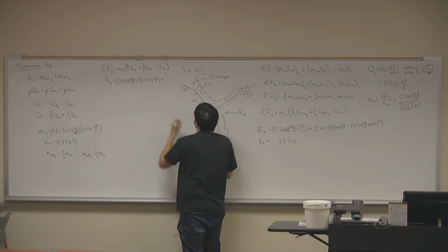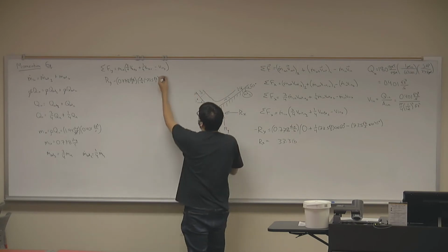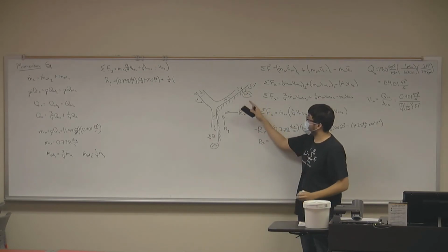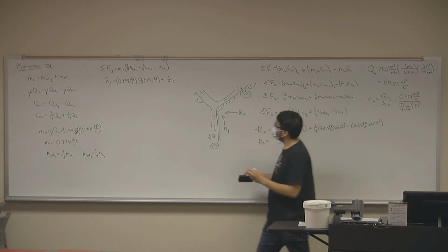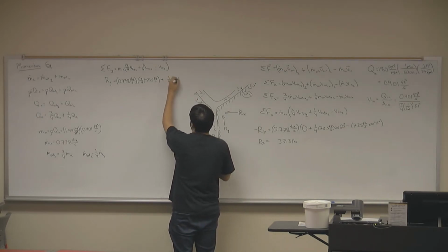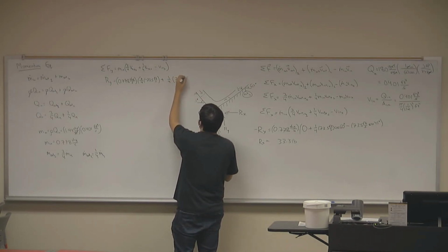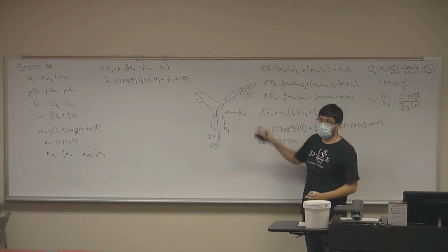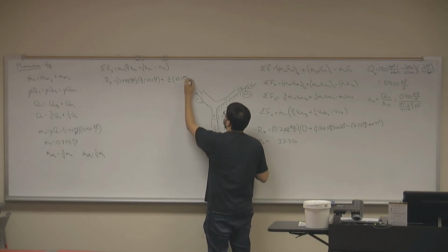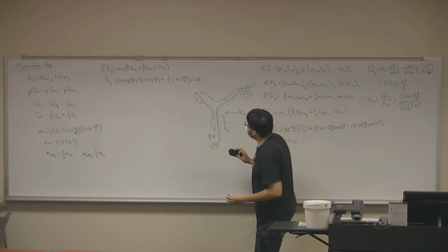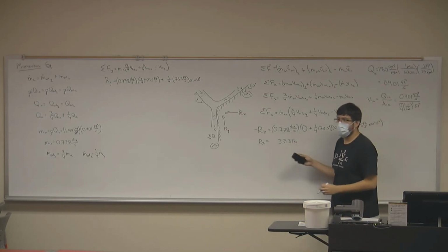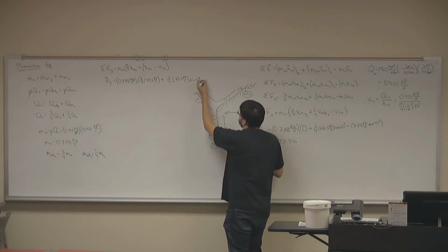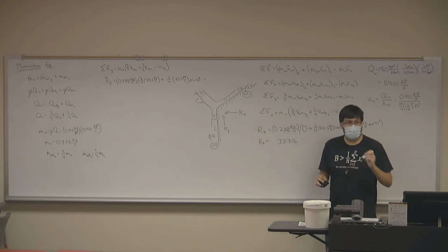Plus, we get 1/4 of the velocity leaving the system through a second outlet in the y direction. What would this component be? In the y direction, what would this component be? This is 60 degrees. What's the y component of this? Sine 60. Okay, there we go. I had a bad dream one day that somebody was answering 0 to that question. But it's okay. It was just a dream. Nothing happened. Nobody heard anything. Minus the y component of the velocity entering the system.